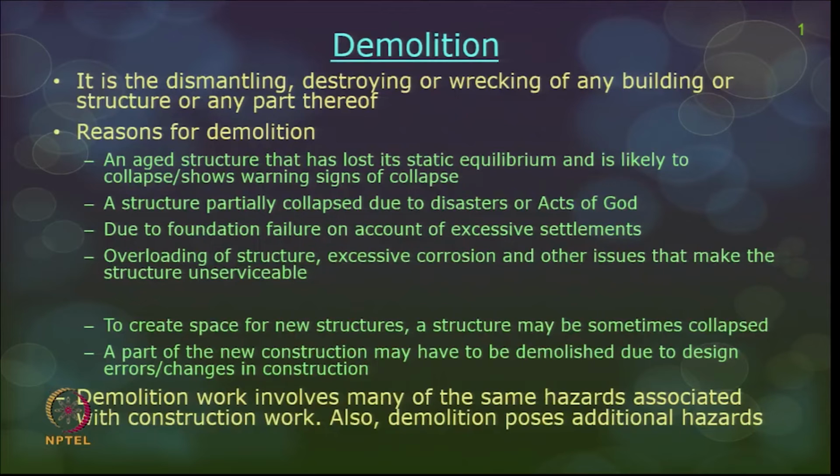Now, what is demolition? We will start discussing demolition and the hazards here. Demolition is the dismantling, destroying or wrecking of any building or structure or any part of it. The reasons can be an aged structure that has lost its equilibrium and shows early signs of collapse, or a structure partially collapsed due to any disaster or act of God, or, the last reason, for want of space.